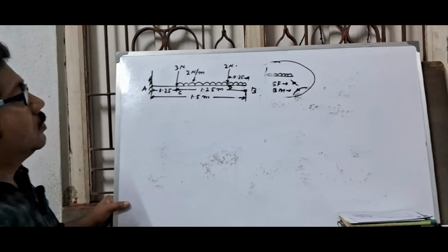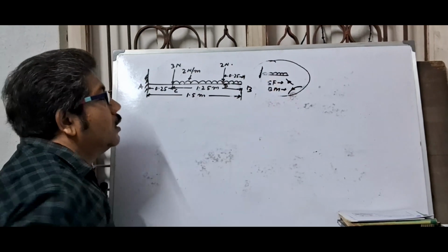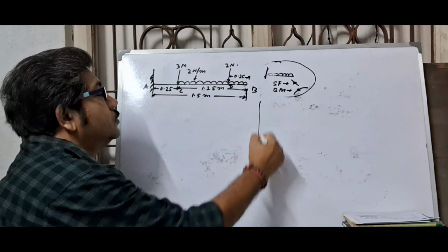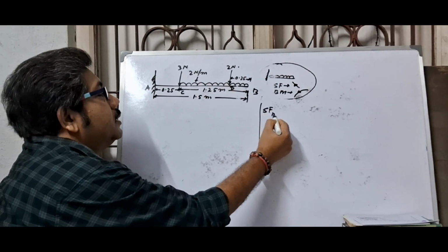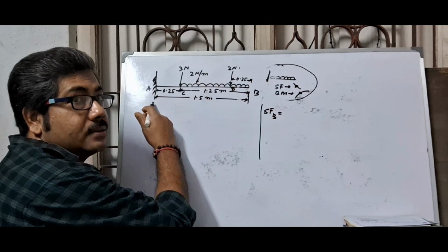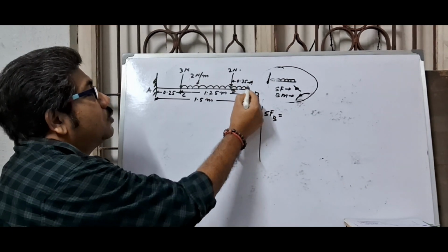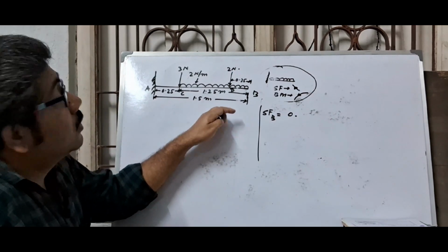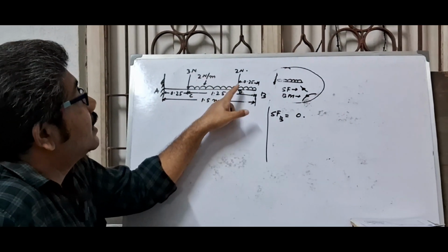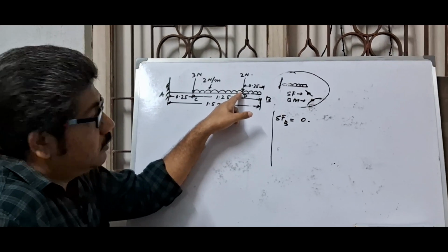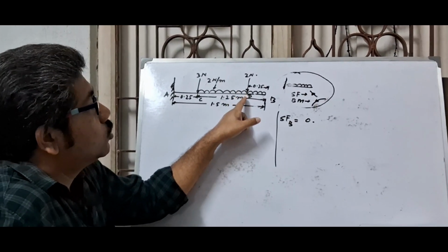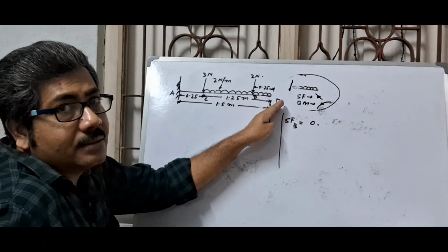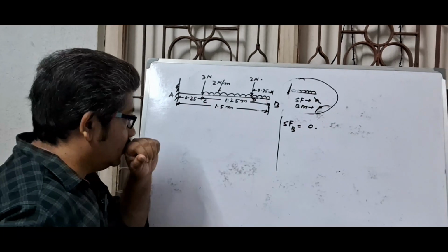Now first of all calculate all the values of shear force. Shear force at point B, from free to fixed end: at point B there is no force here, so this is 0. Remember, when any point load is acting on the UDL, you should calculate shear force just at the right and just at the left.